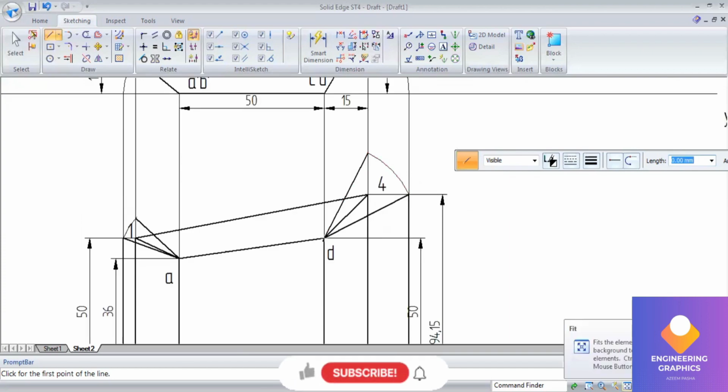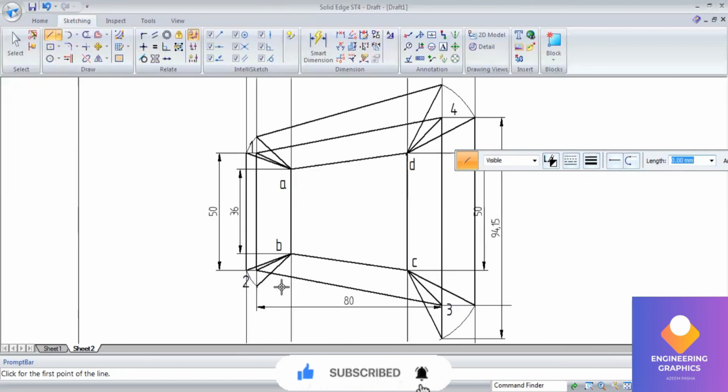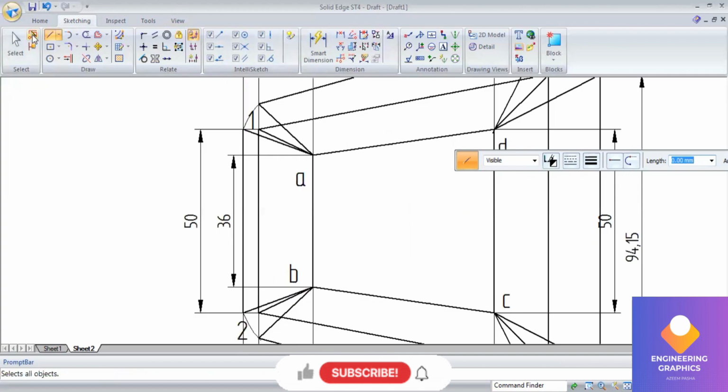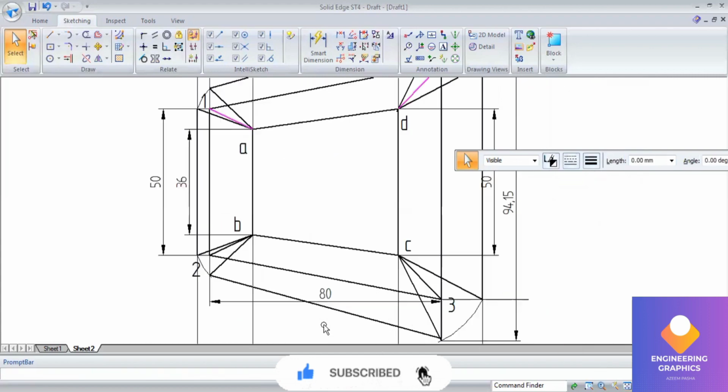Now those intersection points, we should connect with the straight lines here. Yes, from there to there. The same way downward also you have to do the same. From there to there we should connect. Okay. So that completes the problem. You can see that inside lines I'll make as thin lines because this is the actual development of it.